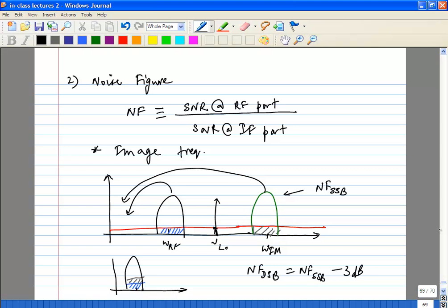So the LNA, when we looked at it, was a linear circuit, but time invariant. It was slightly nonlinear, but it was time invariant. So if you have an input noise and an input signal spectrum, at the output you will have almost the same signal and noise spectrum. Whereas in the case of mixers, VCOs, any kind of switching circuit which is nonlinear, you will see issues with noise folding. You will see noise coming from higher frequencies and lower frequencies into your desired frequency band.